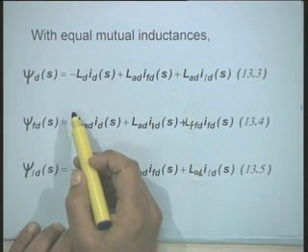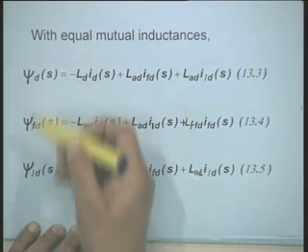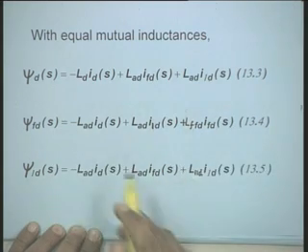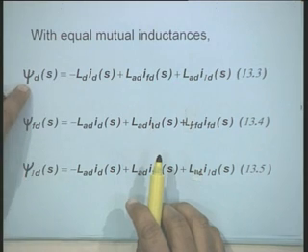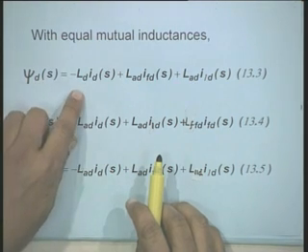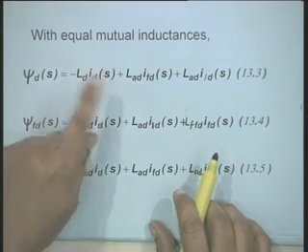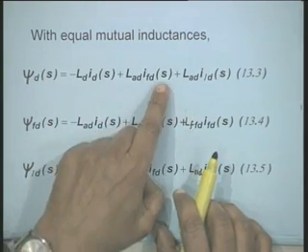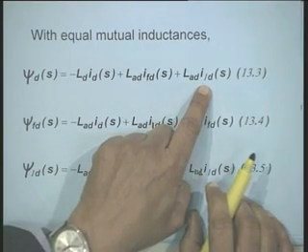We had developed the flux linkage equations. These are now written in the operational form, that is, psi ds can be written as minus L d I ds, the current now being the operational current, plus L A d I f d s plus L A d I 1 d s.